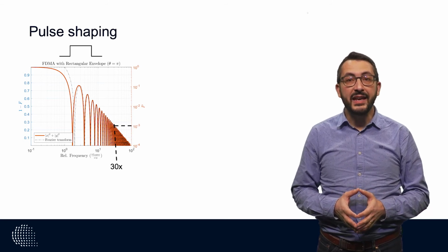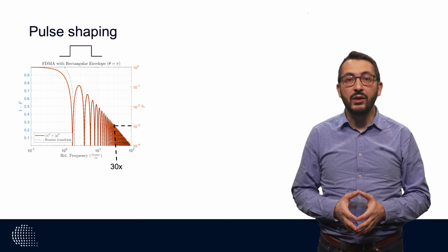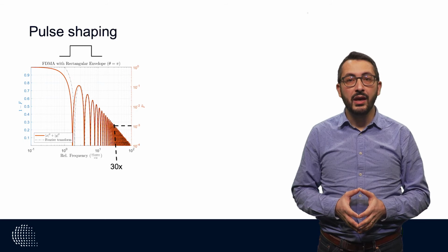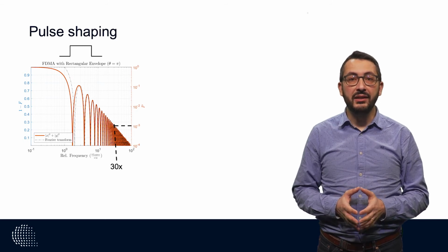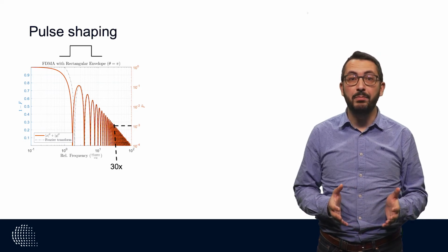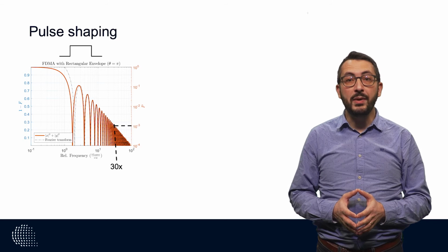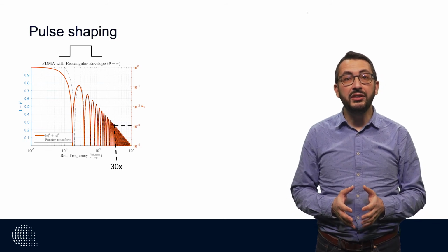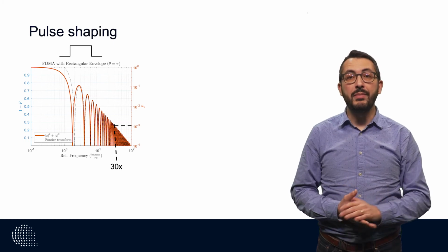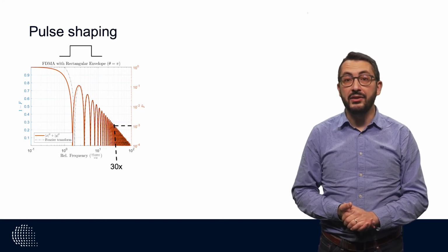That spacing is proportional to the Rabi frequency at which we are rotating the qubit. In this example, if we want to keep the infidelity below 10^-3, that is a fidelity of 99.9% with a rectangular pulse, we need to space our qubits 30 times the Rabi frequency. For a Rabi frequency of 10 MHz, this would be 300 MHz, which is a wide frequency.